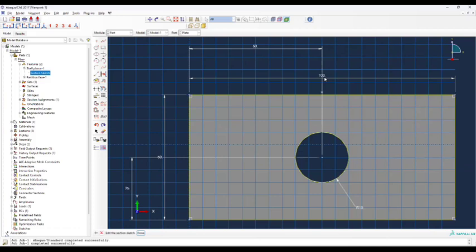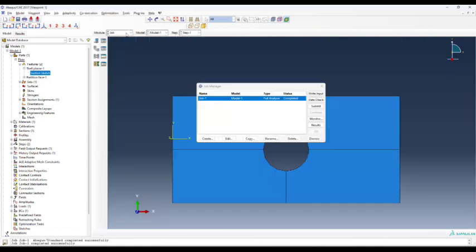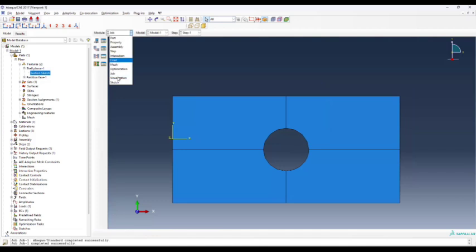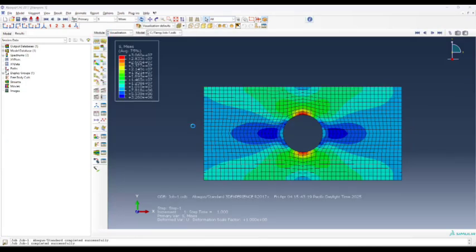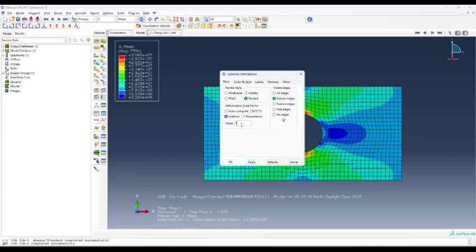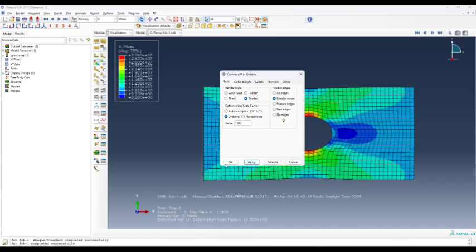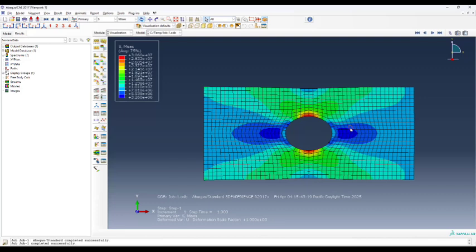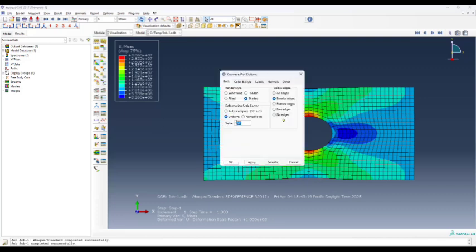Okay. Yep. If you do want a practical value, you would change this to be millimeters. And then at that point you would see a far more dramatic kind of deformation. So you go back to visualization, obviously here. So realistically, we can even play around with the deformation scale factor to get something more realistic. So this is how it would have looked, a bigger kind of deformation right there, right? But with the deformation scale factor of 1, that's how our problem really was.